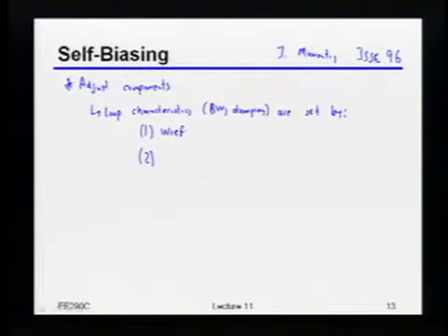In general in CMOS, when you want to do things and make them work well, what do you have to slave them to? How do you make a good voltage divider, for example? Matching. Yeah, you want to make things be set by ratios of identical components, right? So in other words, you want this to be set by ratios of, for example, capacitors, resistors, etc.